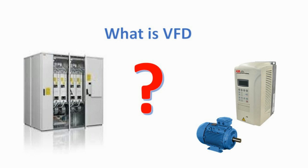There are some other names of a VFD: variable speed drive, adjustable speed drive, adjustable frequency drive, AC drive, microdrive and inverter. Basically, the speed of a motor is directly related to frequency. If an application does not require an electric motor to run at full speed, the VFD can be used to ramp down the speed by decreasing the frequency and voltage to meet the requirements of the electric motor's load.